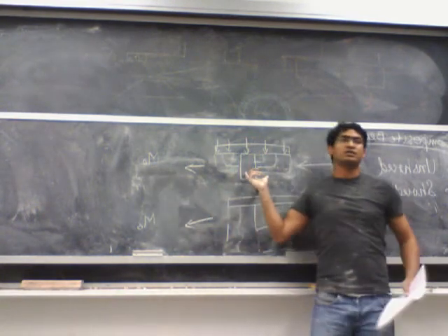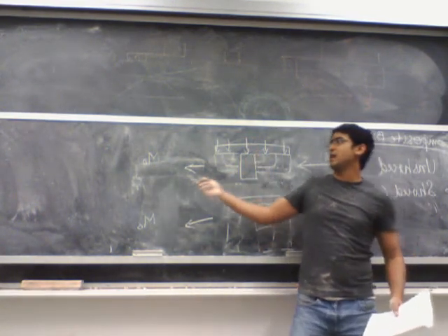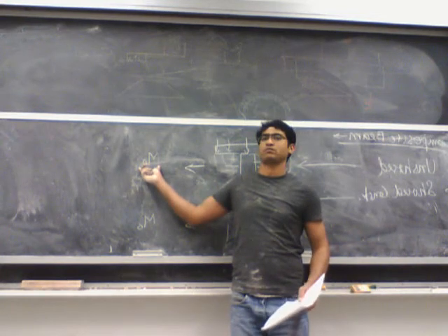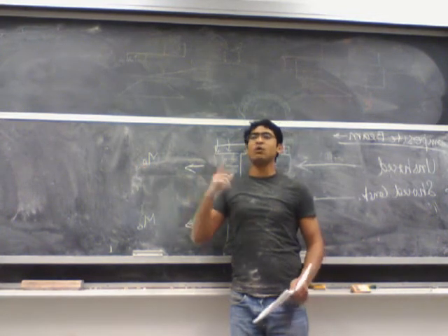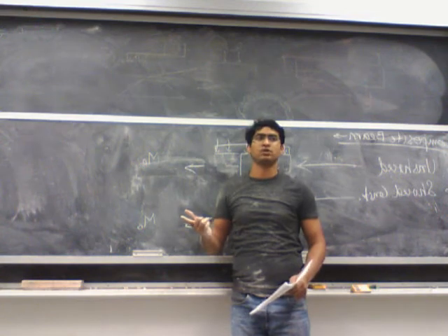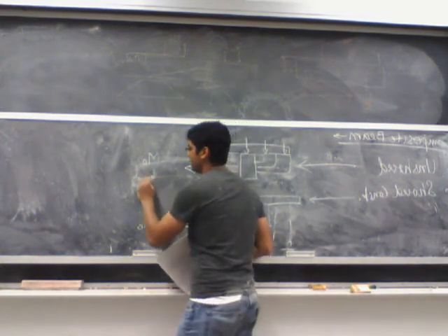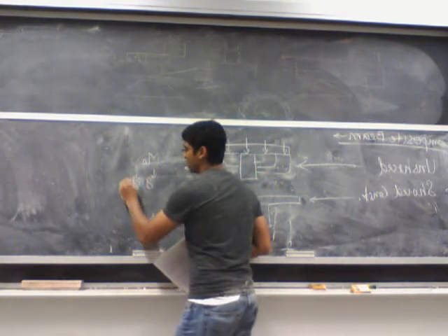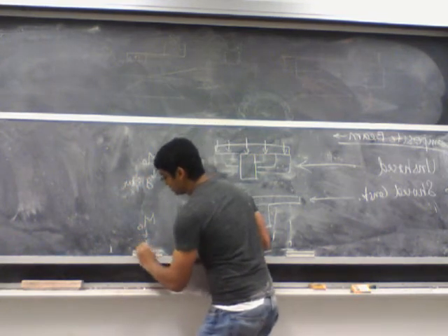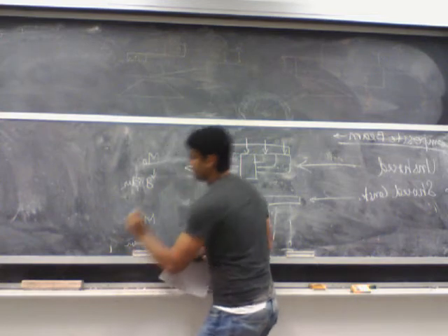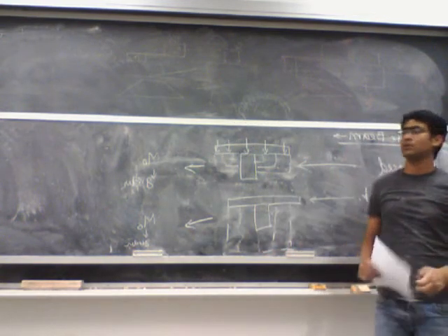What part of the composite section is carrying this self weight to begin with? Initially I only have the girder, so it's only the girder which can carry its own load. So this is carried by the girder only, and in this case also it's carried by the girder.